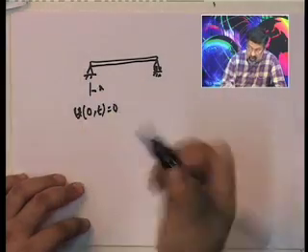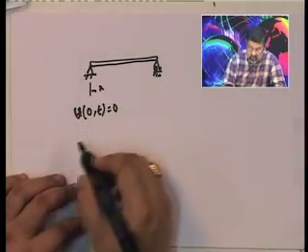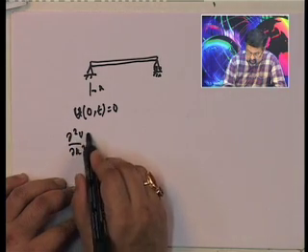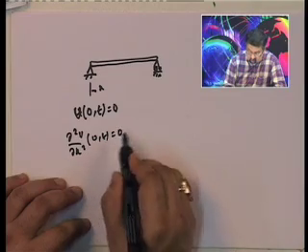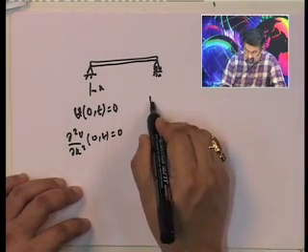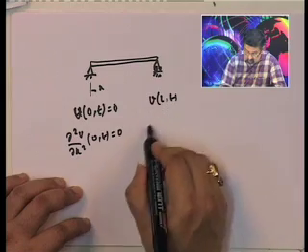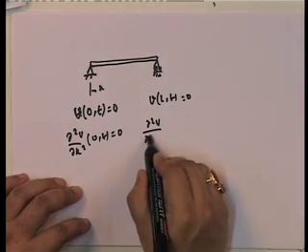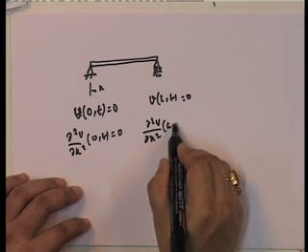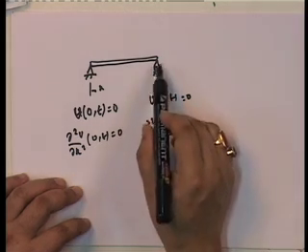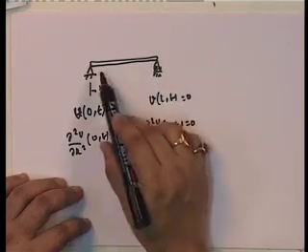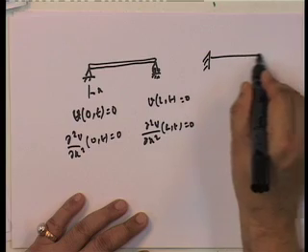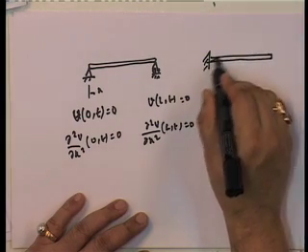I mean, slope I have nothing to do about, but I know moment is equal to 0. So, del squared v by del x squared at 0 of t is equal to 0. Here similarly, v of L, t equal to 0, del squared v upon del x squared at L, t equal to 0, because moment and deflection are 0 in this particular case. Suppose I have this.